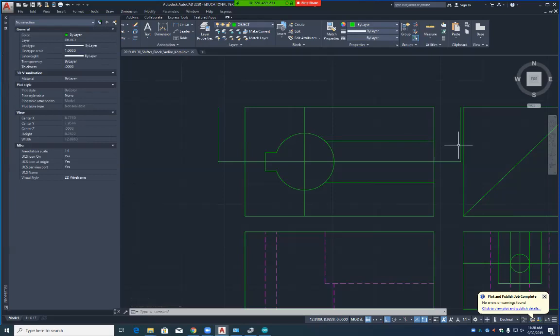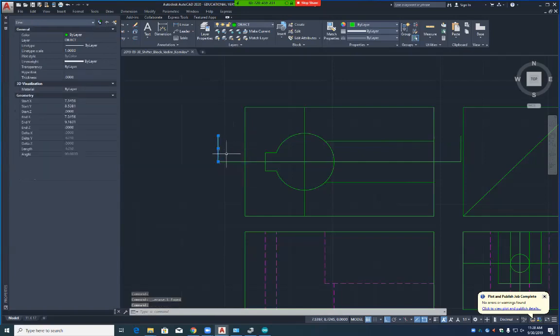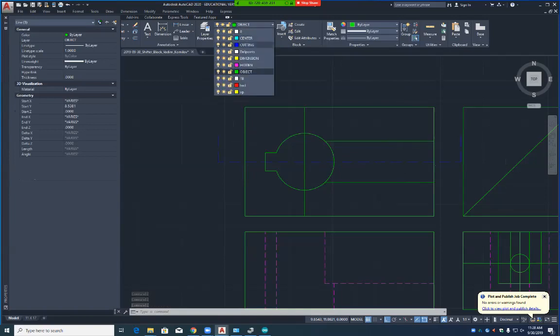Right there. Oh, now, if you look at this, am I right? There's my hidden line. And I said this is half of this right here, and it's approximately half of it, right? So you know you have the right line weight, line types. Because on a cutting plane line, we said it's a 1/4/8. For a hidden, it's an 8/16, 8/16, right? And that's what we've got. So we proved that we have the right line weights and types here. Okay.